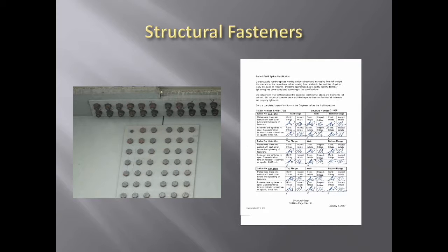The other thing we'll do is do a splice certification. What this splice certification basically says is that all the plies were pulled together in firm contact before the final tightening of the bolt. We'll go through with whoever's out there and show them the documentation and tell them how this is supposed to work. If not, we'll do it ourselves. Most cases, we're the ones that go through and do these. We'll sign them off and buy off each splice as we go through the structure. This is actually supposed to be done before the deck is placed.